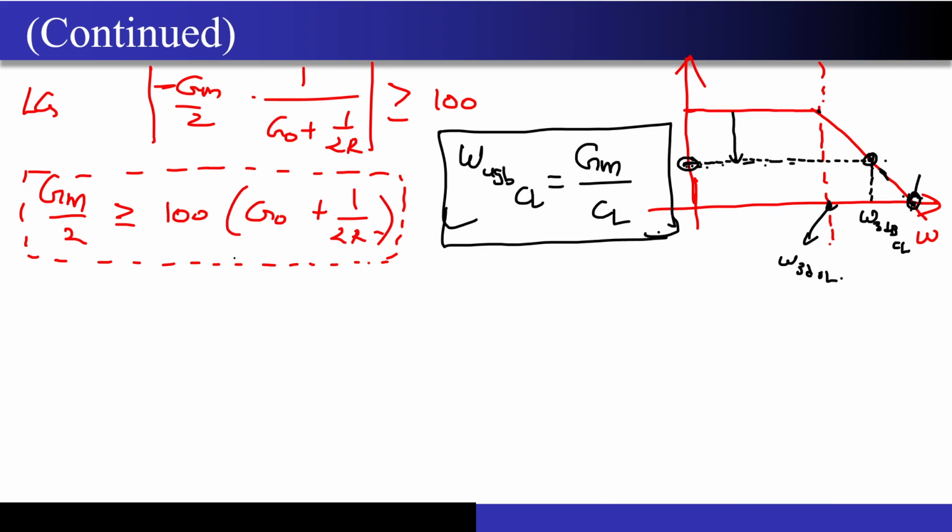Okay, great. So if there are no doubts, then let's try to calculate the gm of the circuit, because we have not yet calculated gm and R out of the circuit. Unless I calculate gm and R out, I cannot get specifications to do the transistor level design. So now what are the conditions that they have given me?